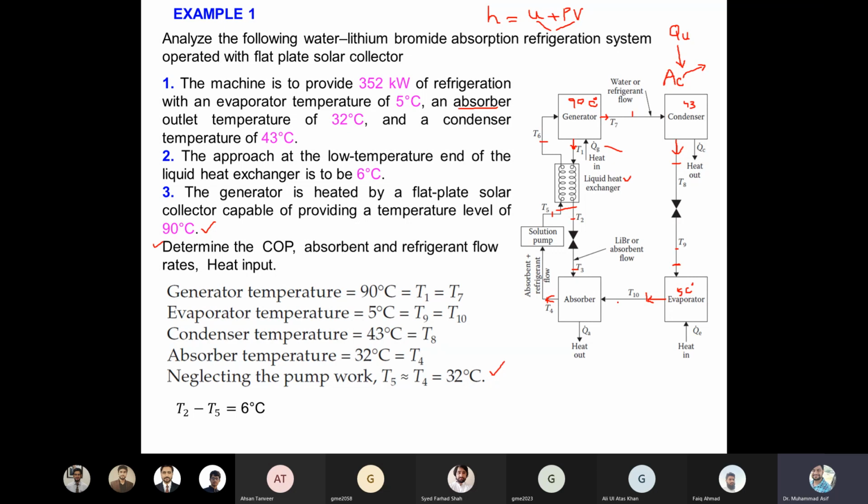So I would answer that this heat is called latent heat. There is a heat which can be taken from a space, from a system, without changing the temperature. Practically, you can ask how it is possible that you are heating a system and its temperature is not changing. That enthalpy is the enthalpy of the phase change, which is used to break the bond of that liquid refrigerant, right?